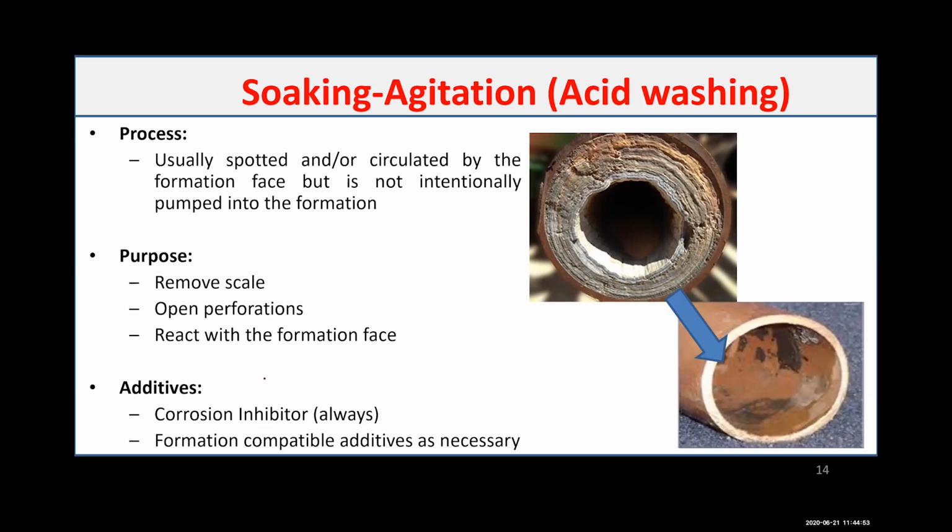The second one is what we call soaking or acid washing. And here we would like to merely clean the tubing from scale. Like I have here a picture of a calcium carbonate scale. You can see this is the tube part, and all this thickness is actually scale.